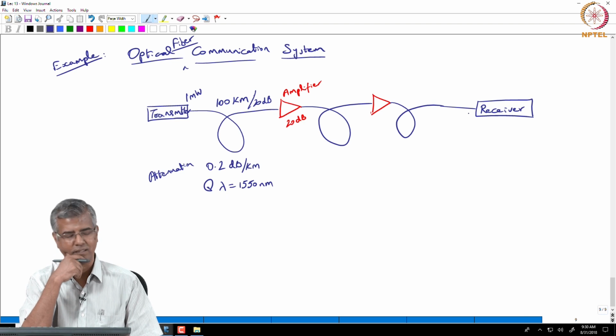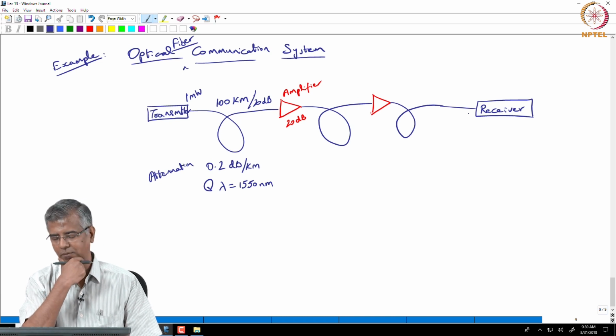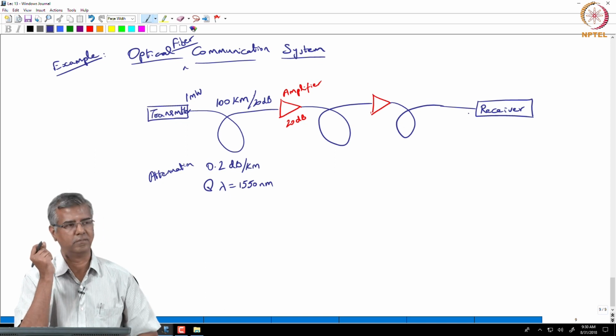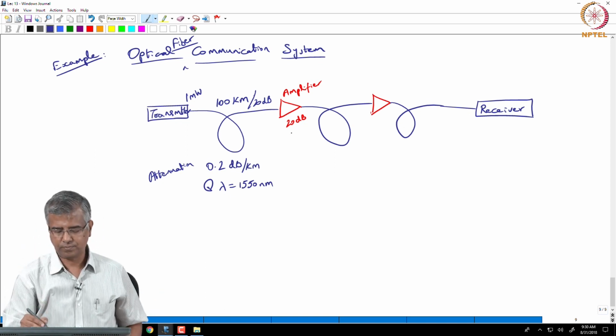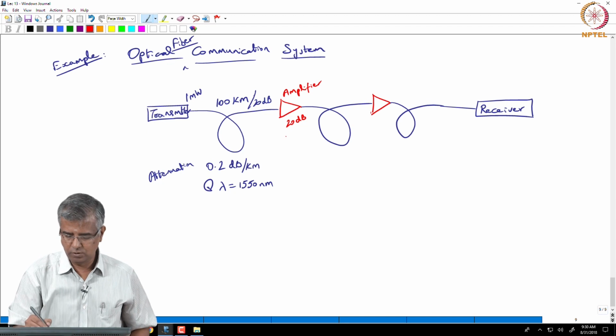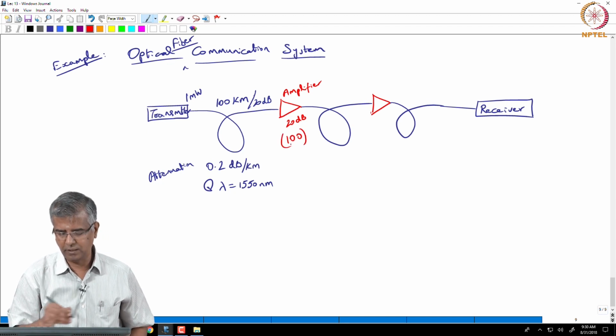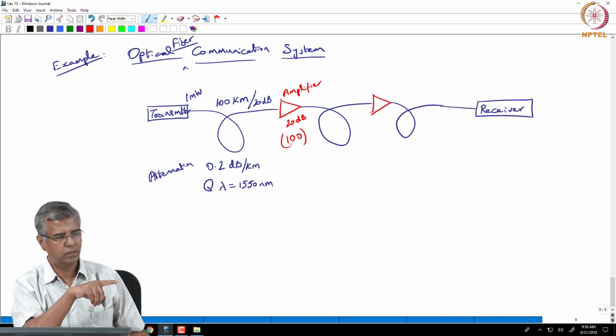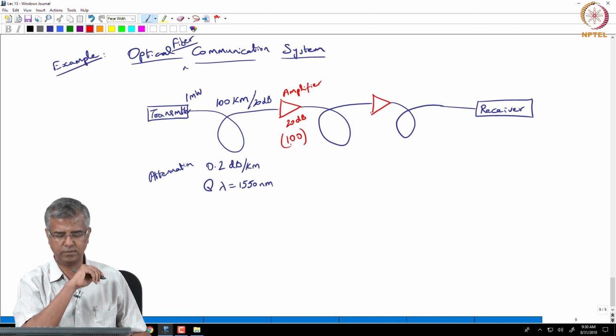20 dB in power, right? It is 10 log is what you take when you do power related measurements. So, 20 dB would correspond to 10 power 2, right. So, that is 100, factor of 100. So, we want to achieve a factor of 100 gain. So, how are we going to do that? But before I do that, you had a question.